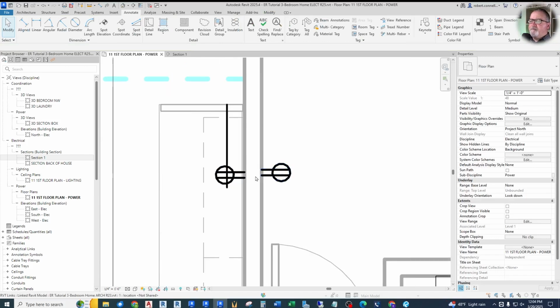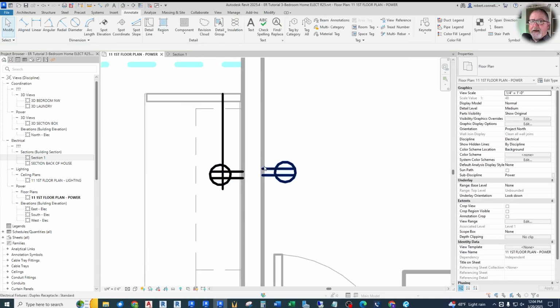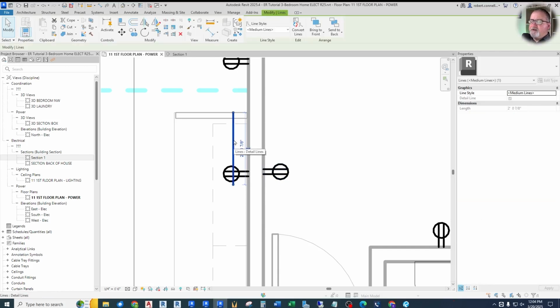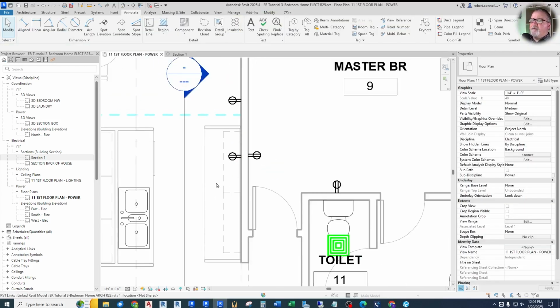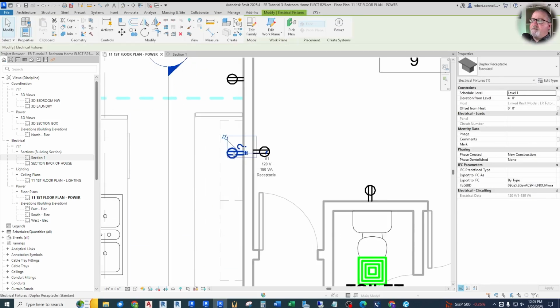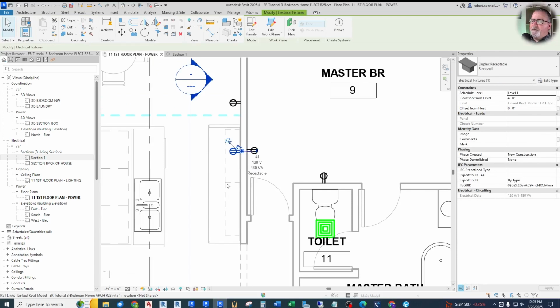And frankly, these are what I call diagrammatic, so they're not exact dimensions, and an electrician is going to take this and actually mount a box typically to a vertical stud that may be anywhere along here. So these aren't super critical. These are approximate dimensions anyway. So let's see how far we are from here. Now we want to go 6 feet. So we're 6 feet 1 inch. So we are just barely going to make it 4 feet between them.